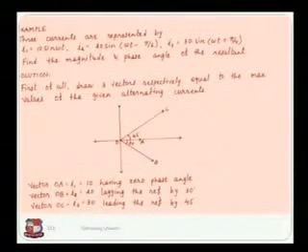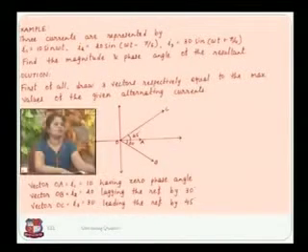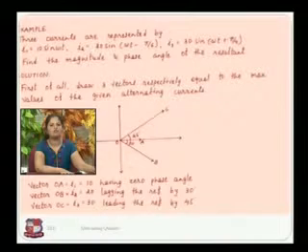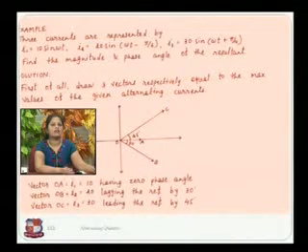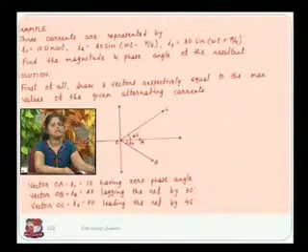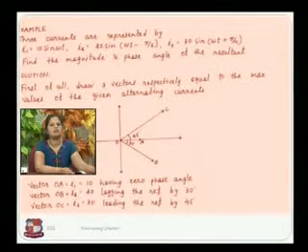Again 3 currents are given to you. First I1, which is equal to 10 sin omega t, I2 is equal to 20 sin omega t minus pi by 6, and I3 is equal to 30 sin omega t plus pi by 4. First current 10 sin omega t means from reference angle the current angle of I1 is equal to 0. For second current it is given omega t minus pi by 6. It will indicate the second current is lagging from the reference axis, and third current is omega t plus pi by 4. It will indicate it is leading from the reference axis.